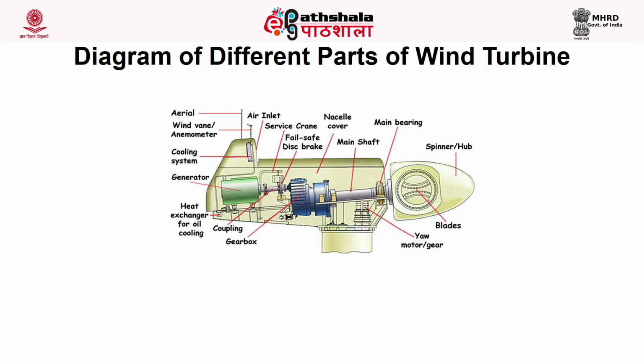Transmission and control. In this part, the rate of rotation of a large wind turbine generator operating at rated capacity or below is controlled by varying the pitch of the rotor blades. The transmission options include mechanical systems involving fixed ratio gears, belts and chains, singly or in combination, or hydraulic systems involving fluid pumps and motors. Fixed ratio gears are recommended for top mounted equipment, and it also consists of the supporting structures. The wind turbine converts the energy in the wind to the rotary.